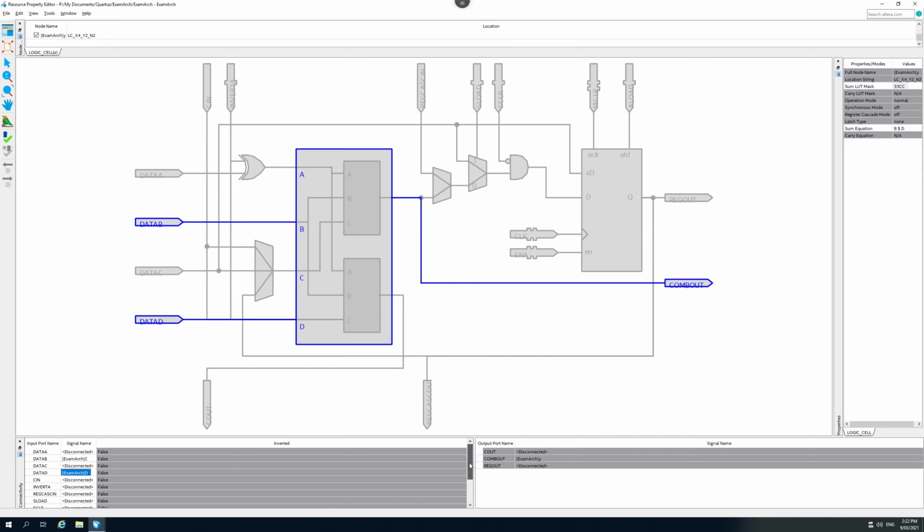If we scroll down here, we see that carry in and all these things needed for doing fast addition or for using the flip-flop are all disconnected because we're not using the rest of this circuitry up here. So it's highly configurable, and each logic element just gets configured to do the task it needs to do. In our case, we have a very simple task: just configure the lookup table to do its job, and then we use inputs B and D to go through here, bang.